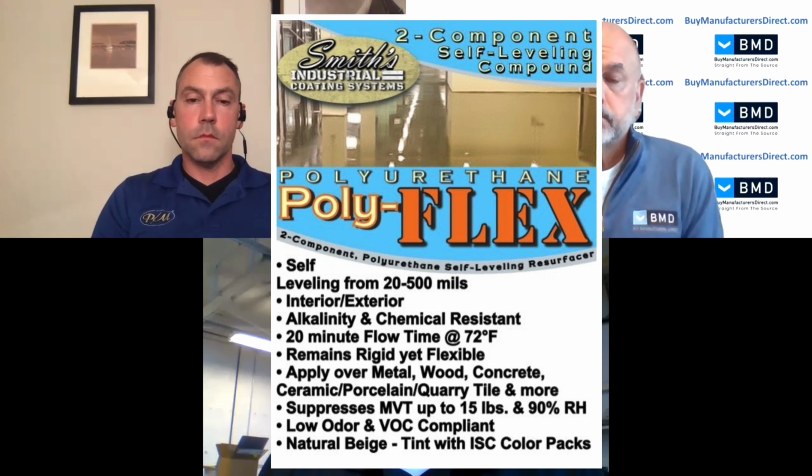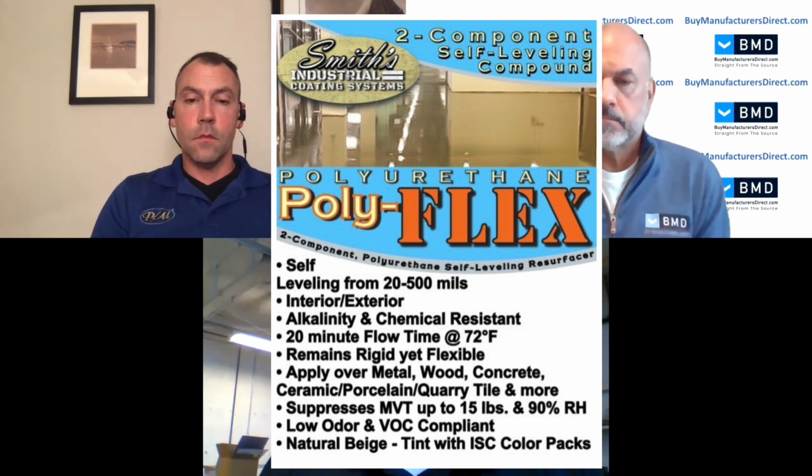So the likelihood of developing a new crack, not saying that there wouldn't be movement that could create a crack, but it's very unlikely that the repair itself would crack. The concrete's more likely to fail because it's weaker than the repair is. Okay. Something bigger, you may get into something like a Polyflex, which is a polyurethane, thicker viscosity material, self-leveling. So that's for deeper fill repairs up to about 5 inches deep.